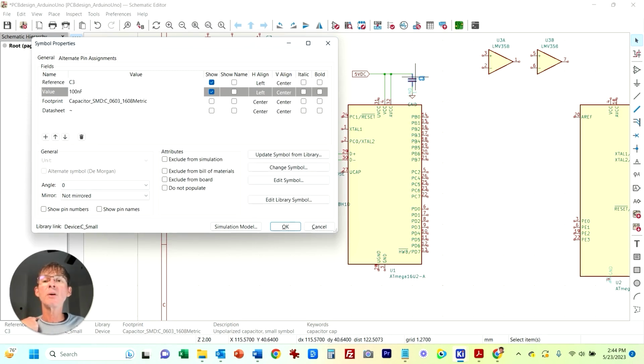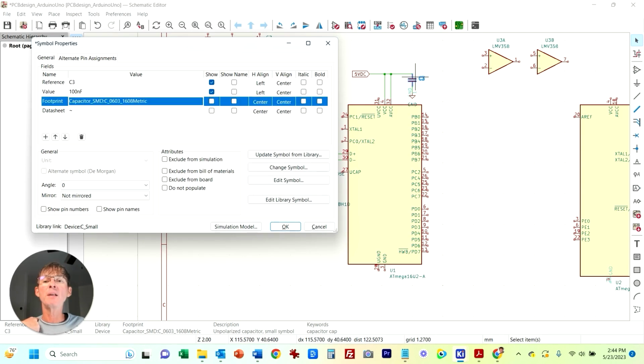And you can see here, I've already got the footprint for this capacitor, and the main number for it is 0603. I know it seems like a really arbitrary number, but that's the size number for surface mount passive components usually. So capacitors, resistors, inductors, and 0402 is another common one. Those are really small. They get a little bit hard to handle. You drop them and you can't hardly see them.